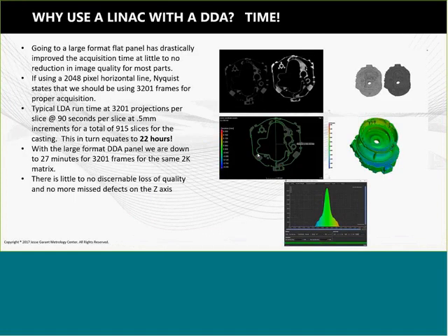Now, this is a question that I get asked all the time. Traditionally, LDAs have been the go-to and are the cleanest form of detectors for accelerators. I fully and wholeheartedly agree that an LDA, or linear detector array, is more efficient. It has better signal to noise and it is cleaner. However, it comes at a great cost of time.